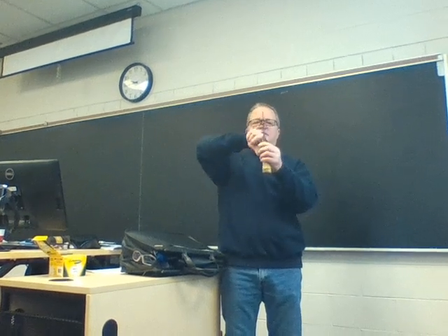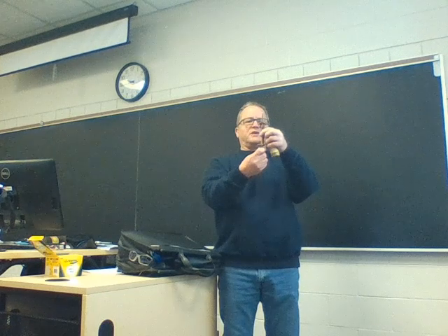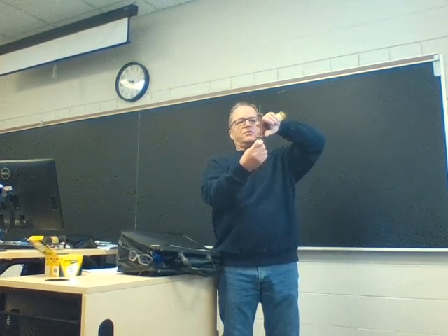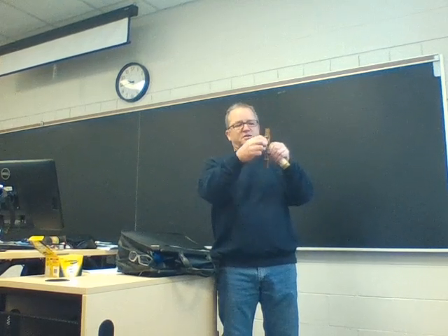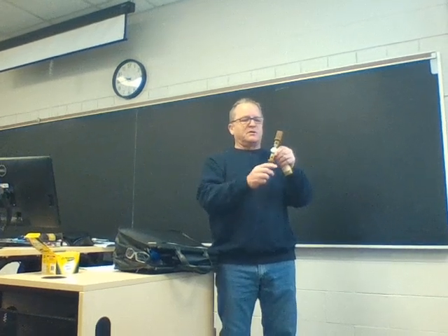The insulating part over here holds the fusible link, so the conductor part of the fuse is from the top through the fusible link and down to the bottom. And the nuts on the face would be where you could replace that fusible link of this fuse.